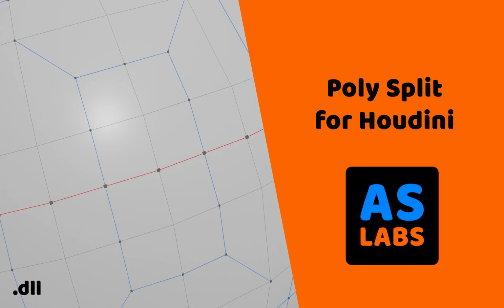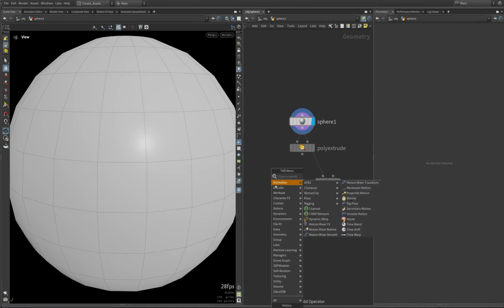Hi everyone, today I want to show you my new plugin PolySplit, which is designed for cutting polygonal mesh in Houdini. Enjoy watching. You can add a node to the scene by pressing the Tab key and going to the AS Lab subcategory.